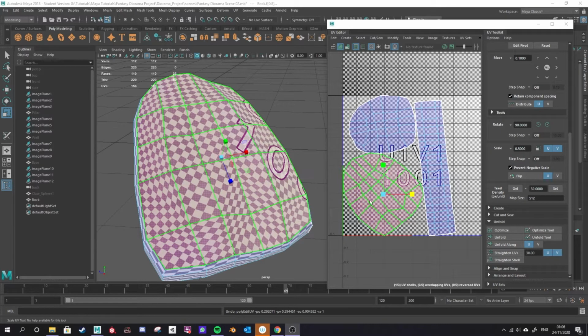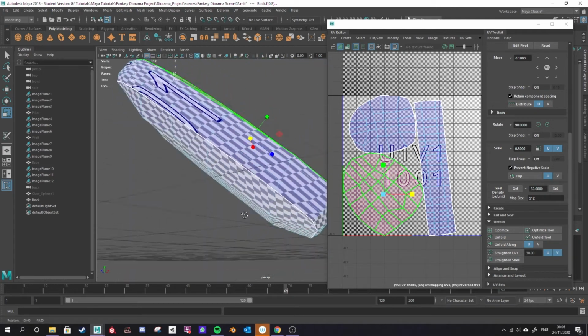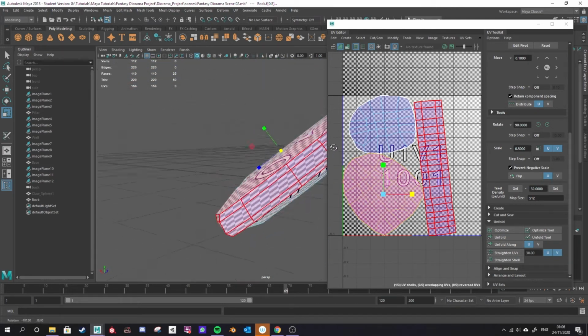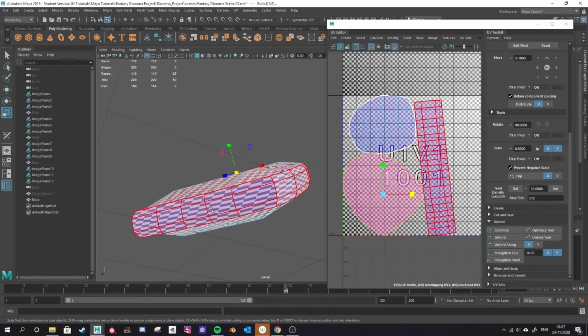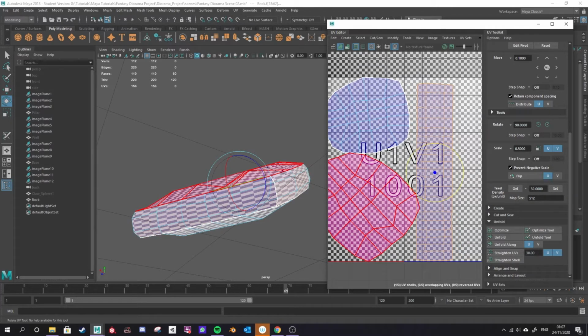Otherwise, when you go to draw on this surface, whenever you draw a line, or say you drew a circle, it's going to elongate it into an oval. So squares is one thing you're looking for. Another thing you're looking for is for these squares to be the same size across the entire shape. So you can see this edge here hasn't unwrapped as well as I would hope. It's quite stretched, the little squares on this. So what I'm going to do is rotate it round. And there are some tools that may help me do this.